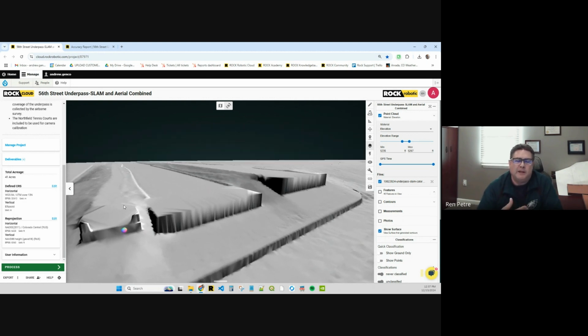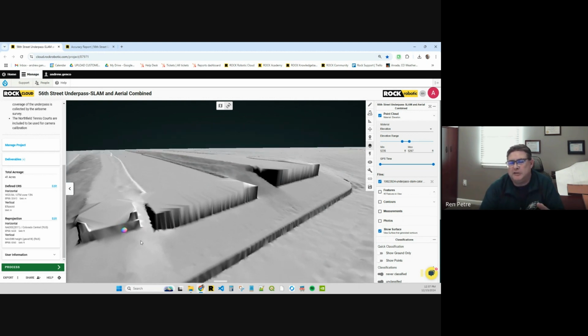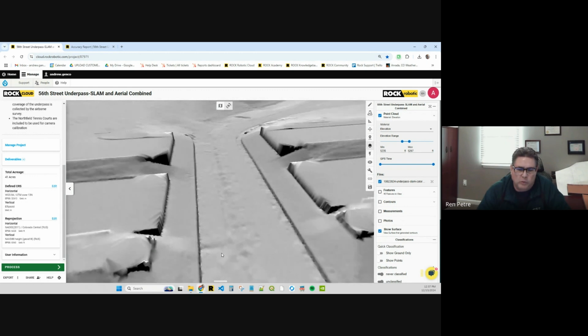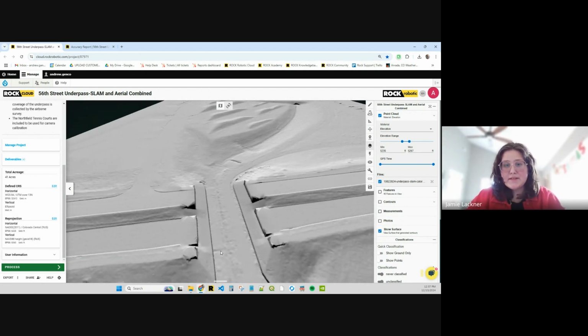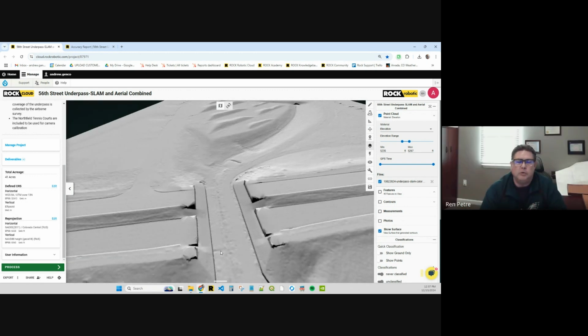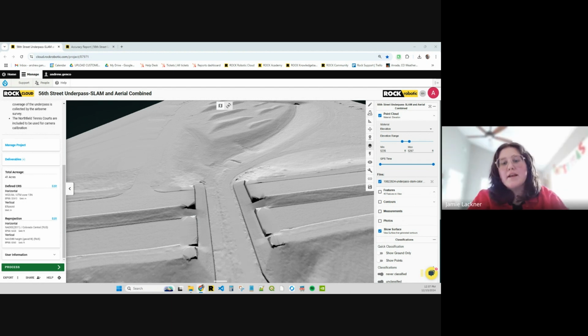I guess what I could do is, if I got a project like this, I can let you know what I would rather hold. Yes, please. If it's a box culvert, just say do the road surface. And as far as when you show the box culvert, all we're going to want are inverts and the outside edges of the box. And then we can just show it as a hidden line running underneath the roadway.